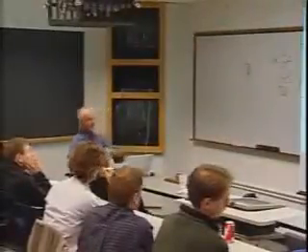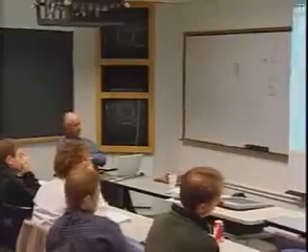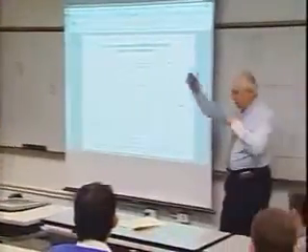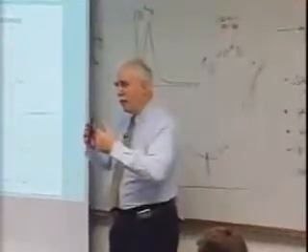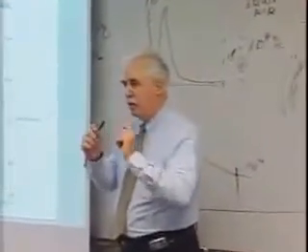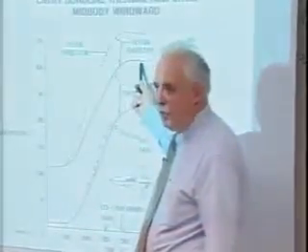Right. I think Tom probably talked about the SIP, the strain isolation pad. I'm sure he did. This is after you diffuse through the tiles and through the bond, RTV bonds through the SIP. This is the actual aluminum temperature. Okay, now I'm talking predictions. This would be the design. This is what the vehicle was designed to experience.